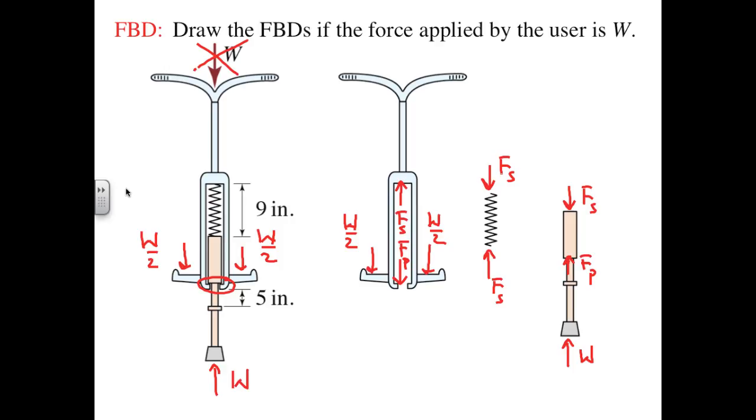As per the specifications in the problem statement, at a weight of 50 pounds, we assume contact is broken between the stick housing and the piston, and F sub P goes to 0. At this weight, vertical equilibrium of either the stick housing or the piston gives spring force 1, which is K times (L0 minus L1) is equal to weight 1.